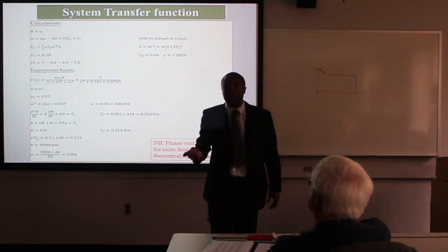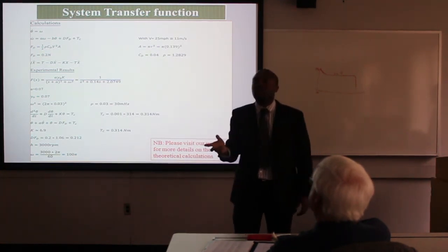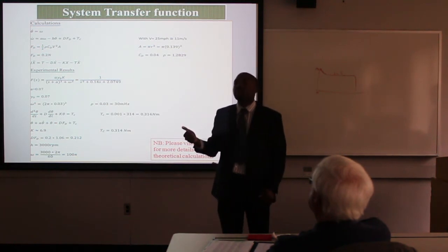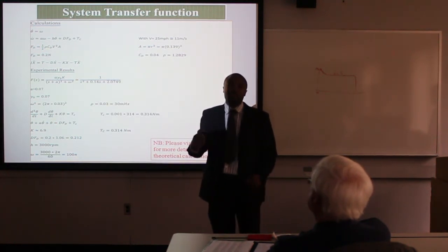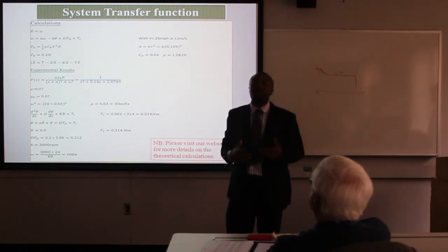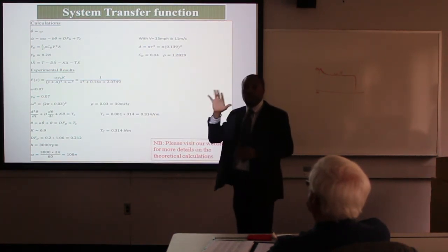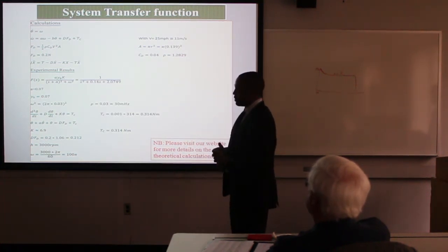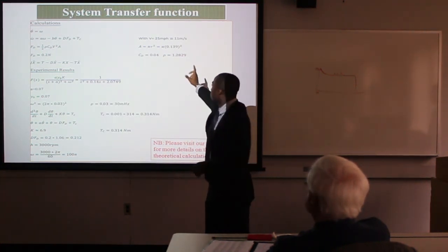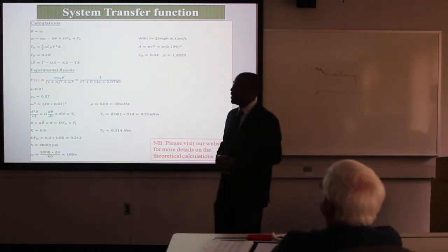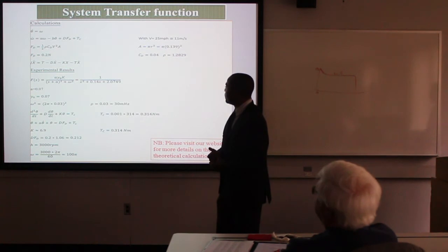The force is called the drag force. There are two forces created once the wind attacks the turbine: the drag force and the lift force. But we're not worried about the lift force, because the drag force is the force that makes the turbine tilt, since it is always parallel to the motion of the tower. So we give this information. The C is the drag coefficient. It's based on the shape of the blade. All this information can be found online also.